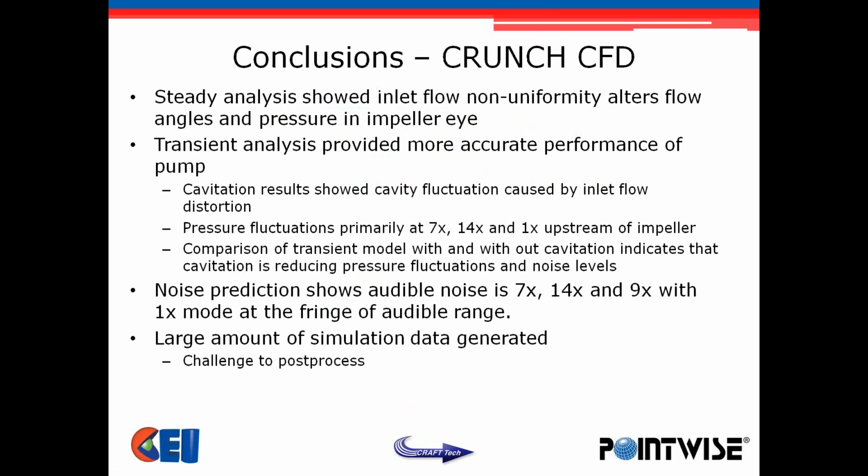So to conclude, we did some steady analyses first to show the non-uniformity of the flow coming in, and we discovered that the design of that inlet affected the flow angles and pressure in the impeller eye. We did transient analyses, both single phase and cavitating, to get a more accurate performance of the pump.